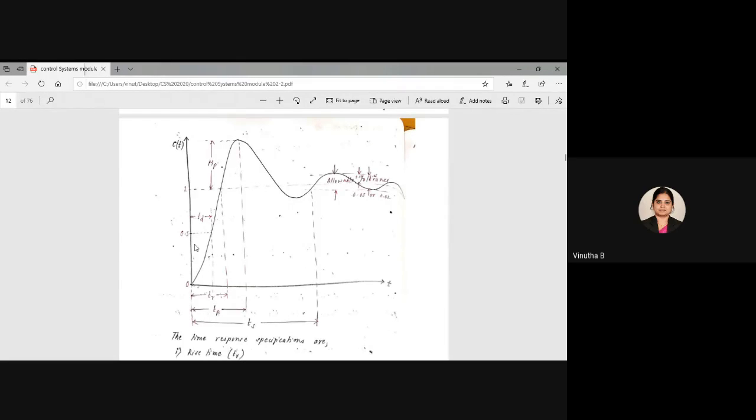Okay, so here at the origin axis, we have 0.5 and 1. This 1 is called the final value. We are going to consider this 1, or this is called 100% of the final value. We have the wave which is generated here and which is oscillating, and this is underdamped. So there is damping here. That means what? The amplitude keeps reducing with respect to the time.